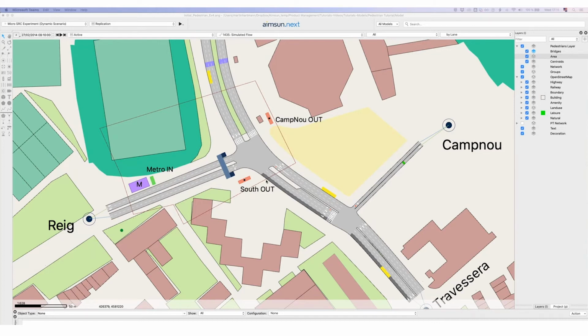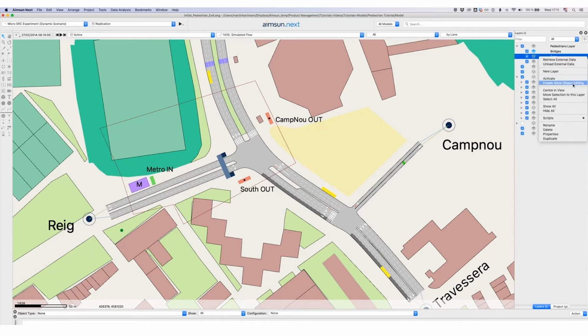For that, I would like to first enlarge the pedestrian area to cover at least 2 public transport stops, so that the pedestrians have the choice between walking towards their destination or taking a public transport line. For that, I will first deactivate the disabled object editing for the pedestrian area and enlarge the area in a way that it covers 2 public transportation stops.